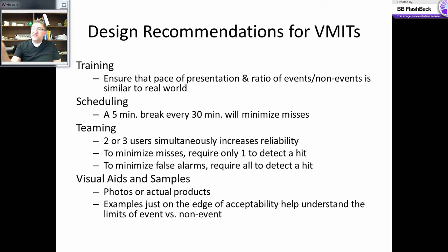Or a miss could also happen. In other words, there is a collision and the sensor does not detect it. It fails in that way, and that happens too. In fact, that's happened very recently with General Motors because of some ignition switch issues. It also leads to moving vehicles running off the road, but there's a failure also of the airbag sensor because there's a power issue that causes it to fail. And you hit a tree or a vehicle or something and the airbag doesn't deploy. So anyway, that's obviously a problem.